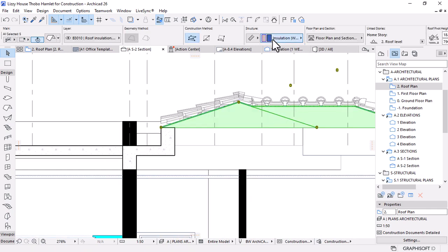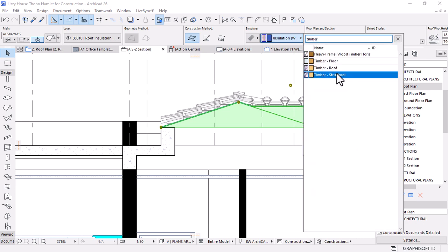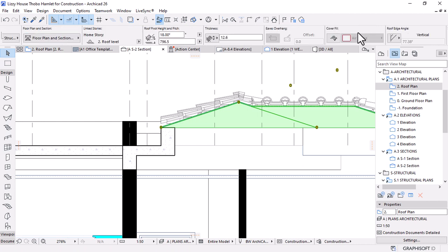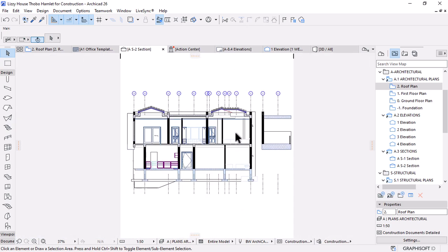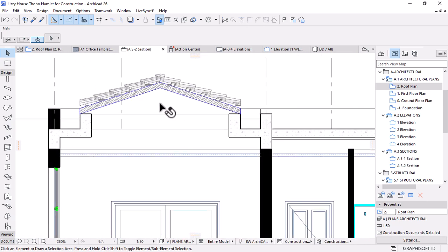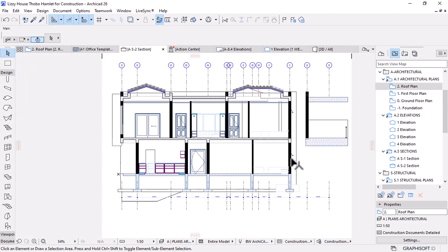Same applies to this one. Set it to timber structural, and then let's set the height to 1:4, which is our region timber measurements. Yes, it looks pretty much the same. And then I can place a note referring this to the specialist, because of course I'm going to engage specialists to do the roof design, roof structure design. So yeah, now I'm pretty happy with the overall section.